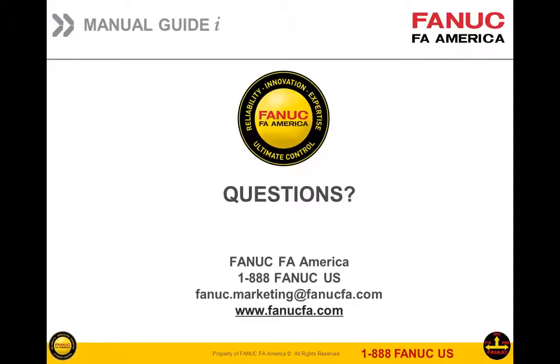How about, can I do a mirror image? Yes, you can. There are several different ways of doing it. Recently I did it for a customer where we put it in a fixed form. The G51.1 turns it on, G50.1 turns it off, and then you tell it which axes to mirror around. Also when you go in and draw a free-form shape, there's a mirror image option there that does the same thing. So if you did a pocket on one side, and you wanted to mirror image it on the other side, you could do that. It's very easy.